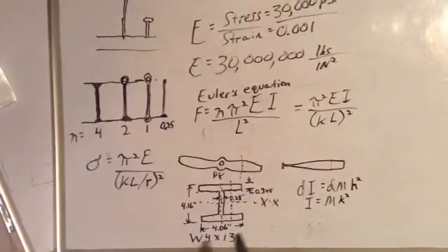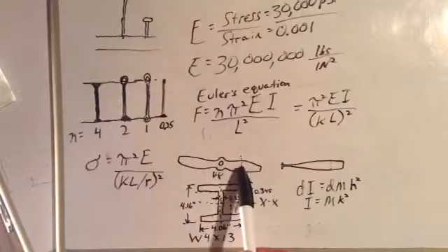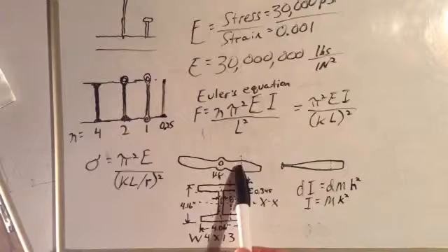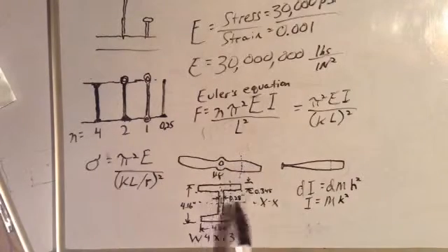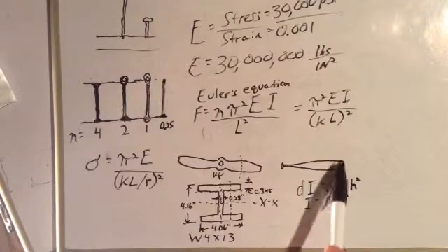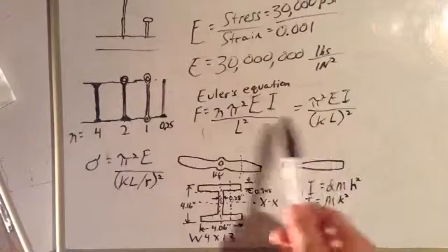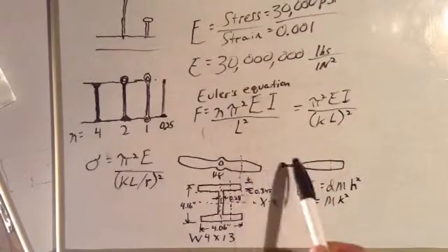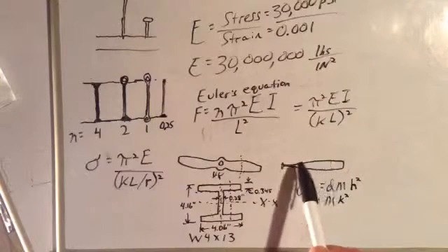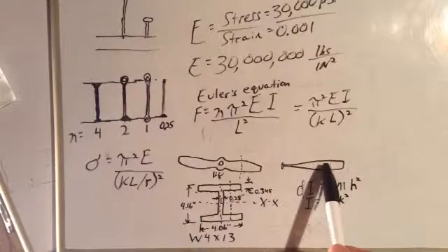Back in our gyroscopic precession lesson, we determined that the mass radius of gyration of our propeller was about 55% of the way from the center to the tip. But with a baseball bat, it would be further toward the fast end of the bat. It'd be sort of like a disc. If we have a disc here, the radius of gyration is going to be 0.707 times the distance between the center and the outer edge, or the square root of 2 over 2.